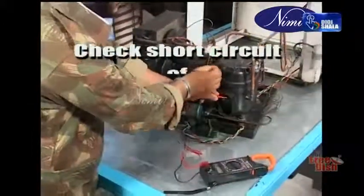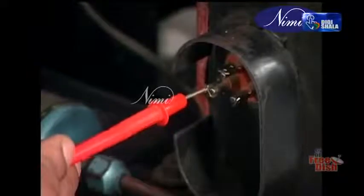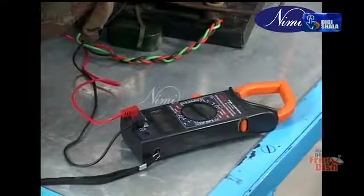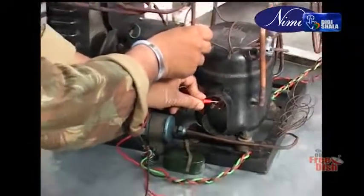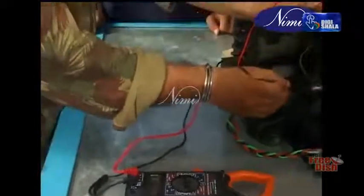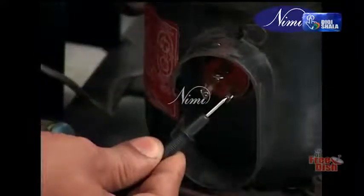Check short circuit of the compressor motor or any other motor. Select one terminal of the motor and touch it with a lead of the ohm meter or continuity meter. Touch the other lead of the ohm meter or continuity meter to the metal casing of the compressor or appliance you are checking. Check the continuity. Is there any? Then the compressor motor is grounded. If there is no continuity, the compressor motor is not grounded.